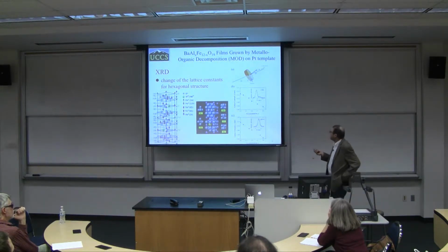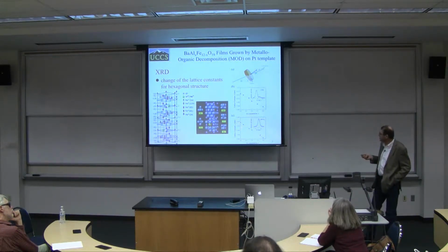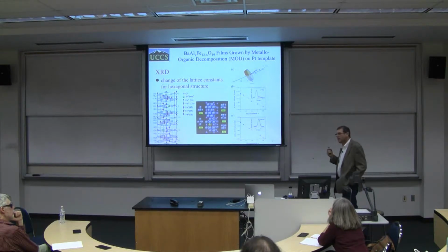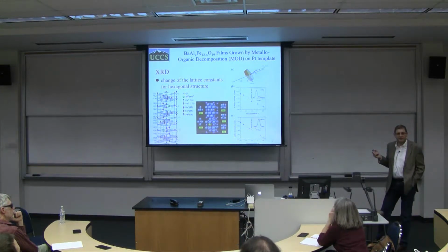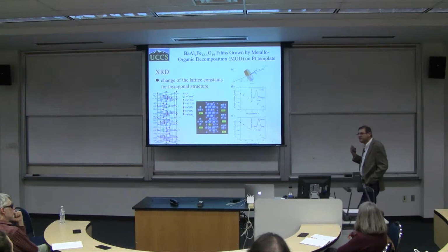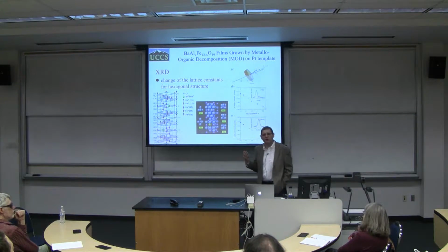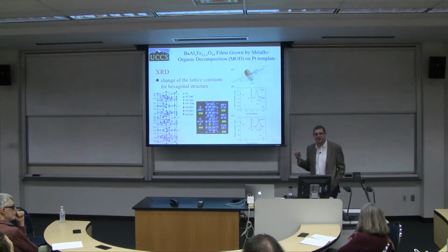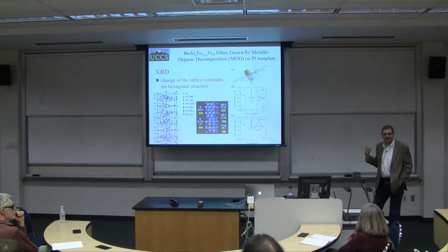Now, what is really interesting is in these measurements, if you look at these numbers, the numbers are in nanometers. So if you look here, we are measuring something which is on the order of picometers. This is our resolution with which we can measure the lattice constant. Now, if you think about it, it's really amazing that we can do this with such accuracy, because average atom size is on the order of maybe 0.2 nanometers. So we can detect extremely small changes in lattice constants using X-rays.